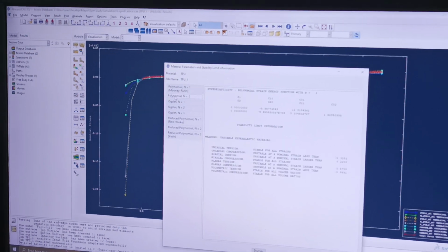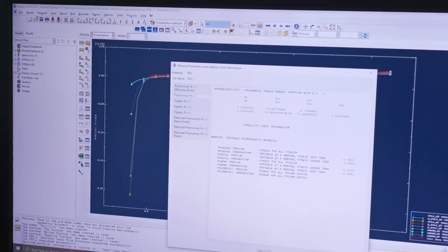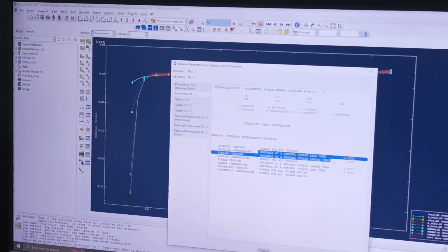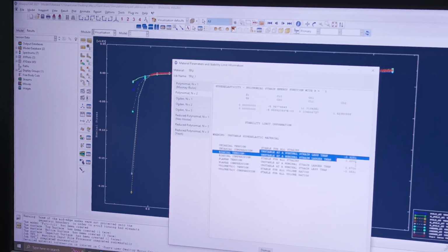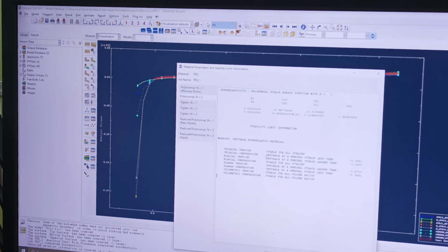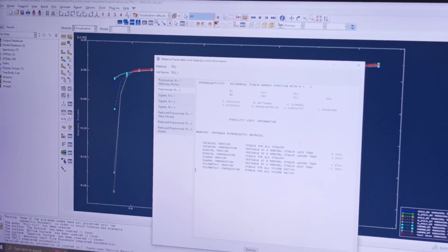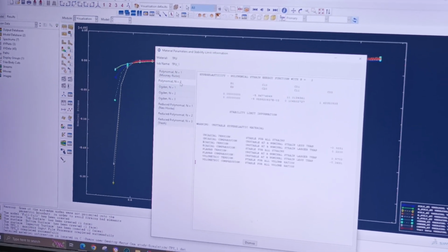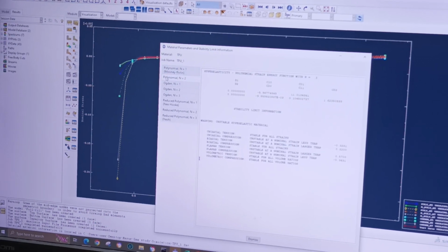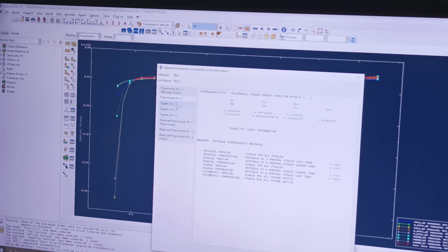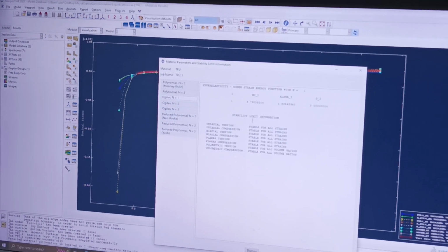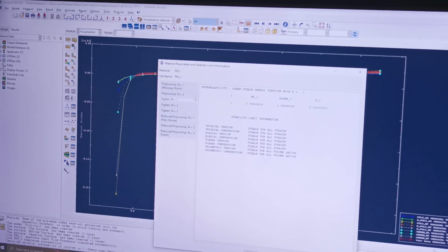You go to polynomial n equals 2, but you see it's unstable at this strain, unstable at nominal strain larger than 0.22. So in some of the tests, they are unstable. So we're not going to use this material model. So n equals 2 is not needed. You see the complexity increases, the stability decreases. Let's look at Ogden 1. Ogden 1 also matches everything.